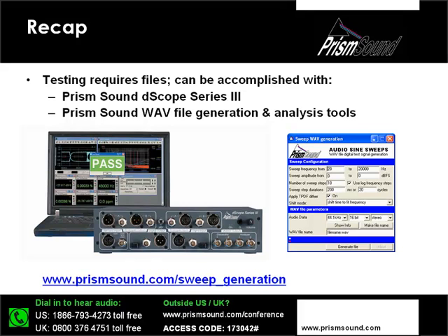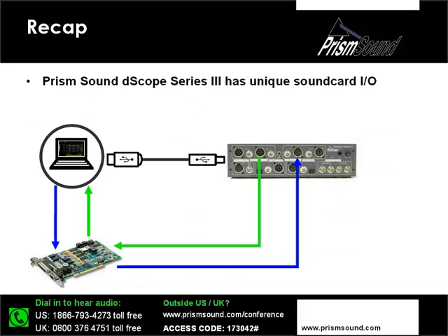And then finally we have seen that if your playback device is a PC type device, either a tablet or a laptop or even a personal computer running Windows as its operating system, we can address the sound card outputs and sound card inputs of those types of devices to allow us to measure in a closed loop in real time, preventing the need to use test files.